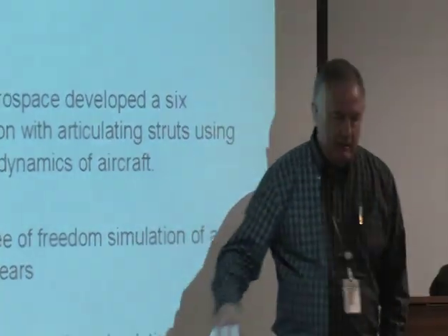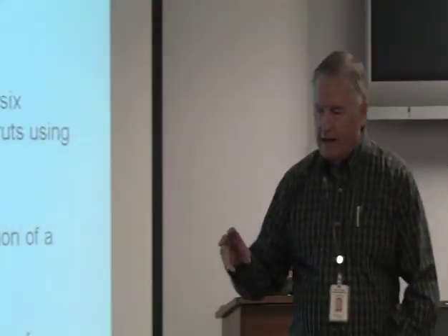If you think of a 4-legged lander hitting, you think the minimum stability is going to be across the foot paths with the lowest overturning radius. So in that period of time, we called it a 2-2 landing, 2 trailing gears, 2 forward gears, going downhill, and that would be the most unstable configuration.